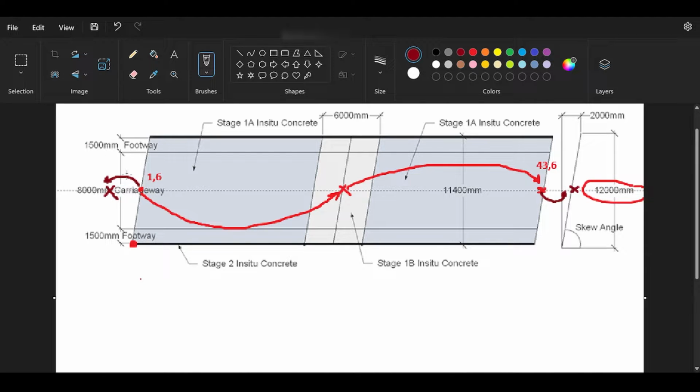The 2 meters are also because maybe I want to have a car driving on the bridge. So I want to model it from back, not on the bridge. I will start my line at -1 and I will end my line at 45 because of numerical analysis issues and because of the bridge car itself.